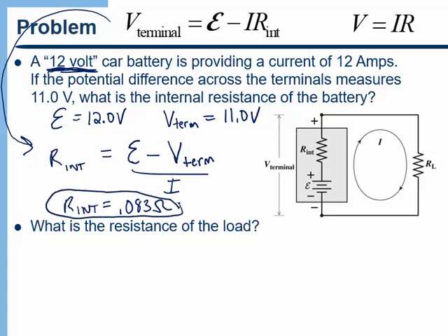Now, by the way, again, this is just a model of how a battery works, but one of the things you find with something like a car battery is that as that battery gets older, the effective internal resistance increases. And that's why at a certain point, when you try to draw enough current to start your car, so much of the voltage is lost internally that the starter is no longer getting enough current to actually turn over and start the motor.